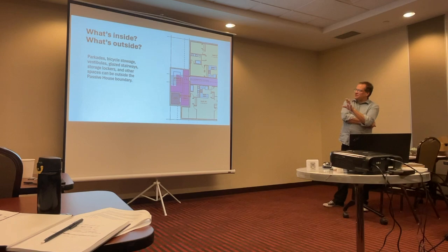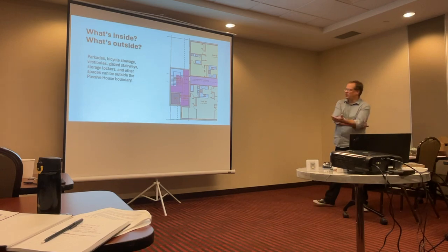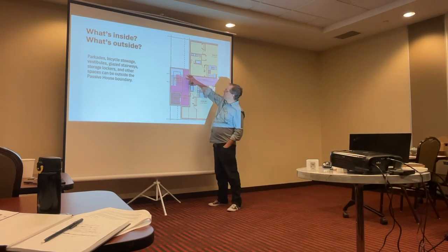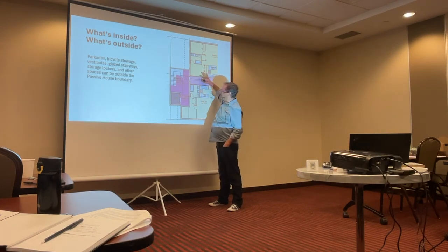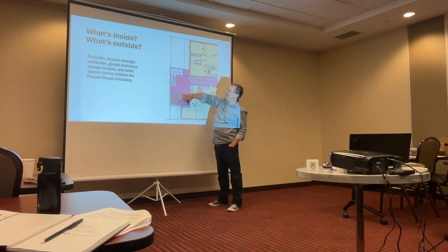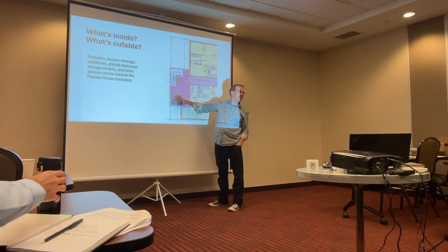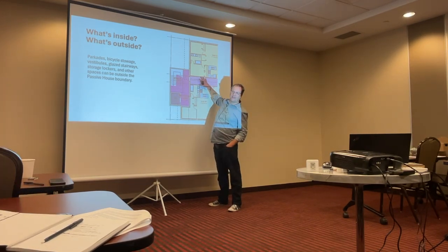I do want to have a discussion in the book and in the workshop on what's inside and what's outside the enclosure area. It's come up on a lot of our first-time projects. One project thought it would be great to take the stairs and the elevator outside to keep the building really controlled. The problem was, the elevator, in order to stay warranted, had to be at 14 degrees C or better year-round. This project was in Whistler, so they were going to have to heat the glass box to put the elevator out there. It made a lot more sense to pull the elevator back in, although still leaving the stairs outside.